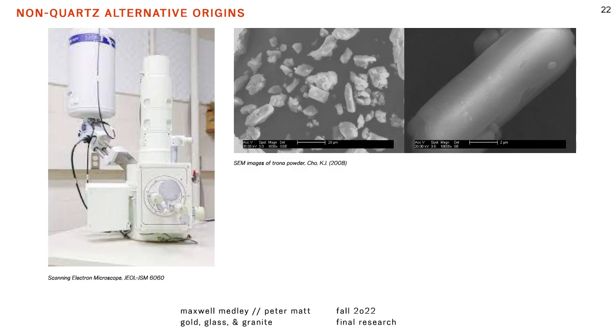By using an electron microscope, researchers found that crystals with different geometric shapes and dimensions were observed in the trona powder sample. When researchers melted down the trona quartz mixture, sodium silicate cullets were obtained successfully. In this study, the trona glass was most effective when melted at 1200 degrees Celsius, which is actually higher than the industry standard for glass cooling, usually at 1100 degrees Celsius. This means that trona glass could potentially be more effective at resisting heat transfer, although the literature in this regard is still rather narrow in volume.